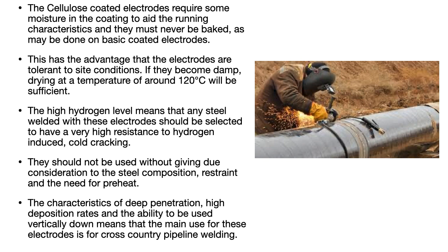In most cases with cellulose electrodes, baking is not recommended, because they require a certain amount of moisture in the coating to aid certain other characteristics.